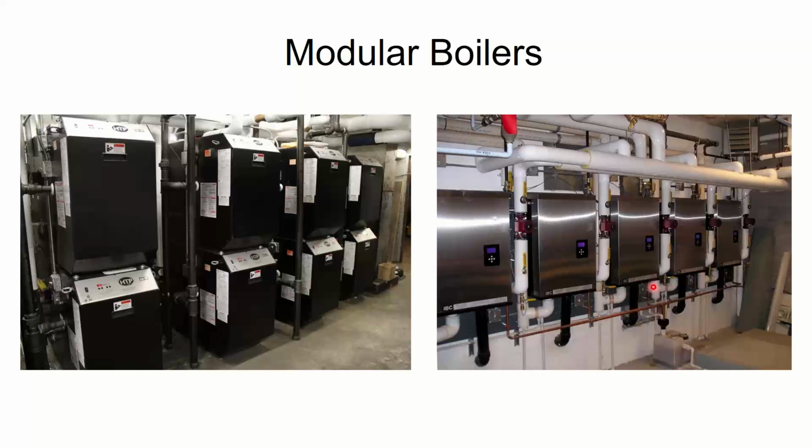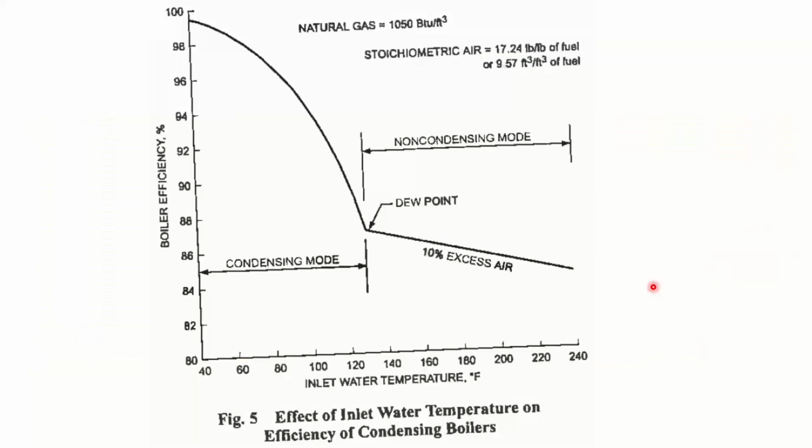We'll put modular boilers in and have a bank of, in this case, what is it, 8 on the left, or this other plant has 5 boilers on it. 5 boilers may be serving 72 radiators that are also served by 6 rooftop units or something like that. 6 rooftops, 6 thermostats. The radiators that are in that area for rooftop 1 go with the thermostat for rooftop 1. Pair them up evenly.